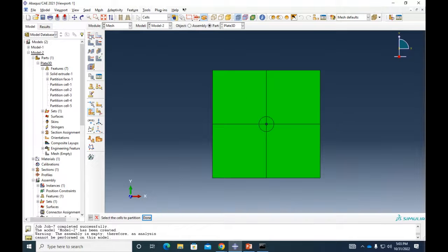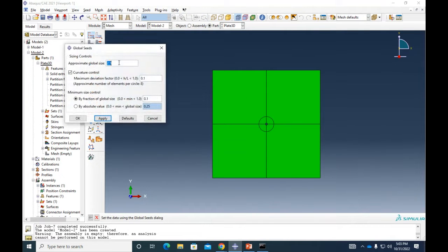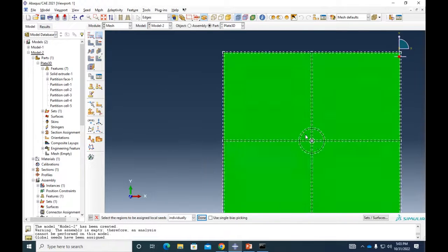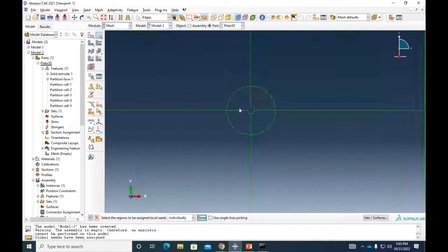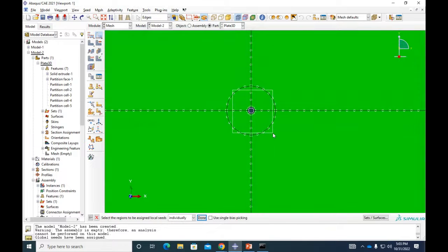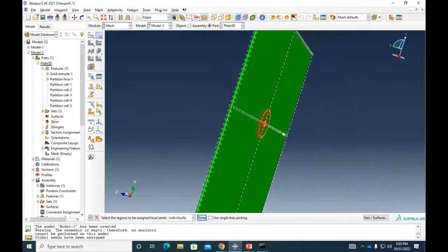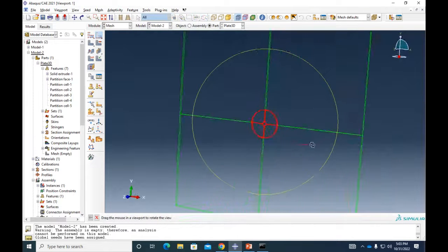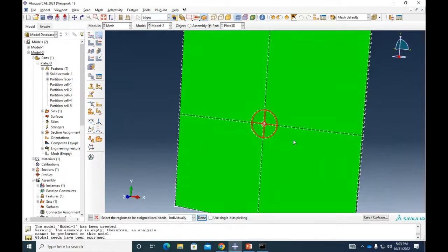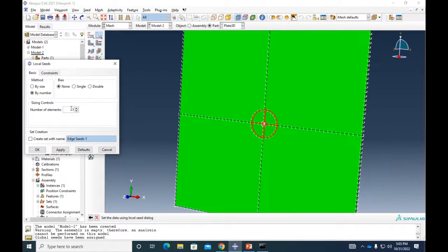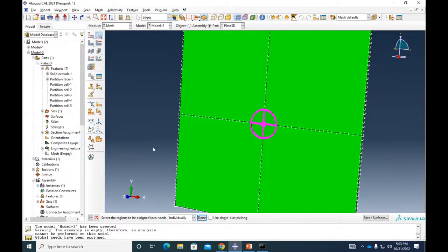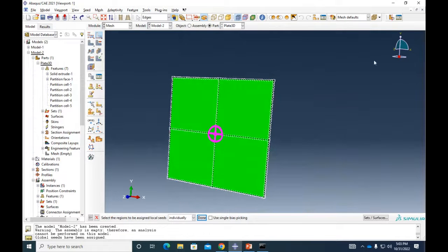Okay, quickly, let's add a global element size of 2, and let's create some smart meshing around this region. Same as we did before. I'm going to select this, and whenever I'm selecting on that face, I'm also selecting everything, right? Because it's now 3D, so it's not only what you see in front, but also from the back. And let's say that we have 100 elements. I don't want the super accurate solution in here.